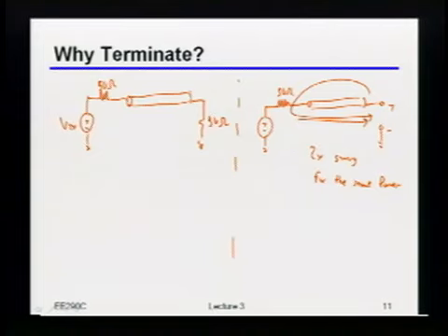So indeed, for most links that you're likely to encounter, they probably will terminate both on the receiver and on the transmitter, even though that implies that you pay a fairly substantial penalty from a, let's say, swing versus power standpoint. Okay, and that's really just, you want to be robust. There's kind of no other great way of ensuring that that's the case. Okay? Does this make sense to people, or?